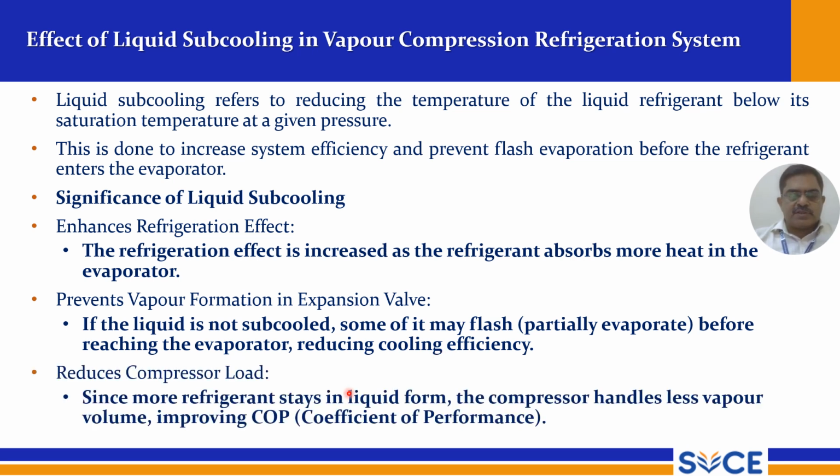It also reduces compressor load. Since more refrigerant stays in the liquid form, the compressor handles less vapor volume, improving the coefficient of performance. So it improves the COP, and ultimately it reduces the compressor load. The refrigerant stays in liquid form, and the compressor handles less vapor volume, improving COP. So that is another advantage here, students.